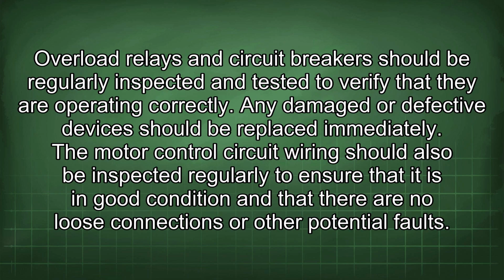Overload relays and circuit breakers should be regularly inspected and tested to verify that they are operating correctly. Any damaged or defective devices should be replaced immediately. The motor control circuit wiring should also be inspected regularly to ensure that it is in good condition and that there are no loose connections or other potential faults.